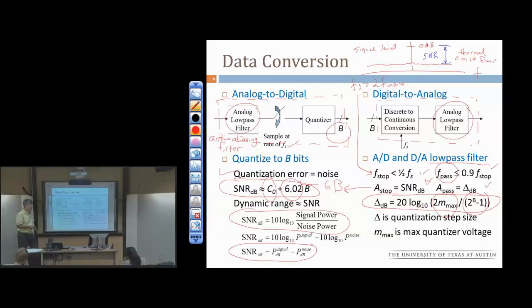Okay, so if you think about QAM as two-dimensional PAM, then it helps make this a lot easier. So consider QAM. If I have 1 bit in the in-phase component, I have 1 bit in the quadrature component. And they're orthogonal to each other. They don't see each other.